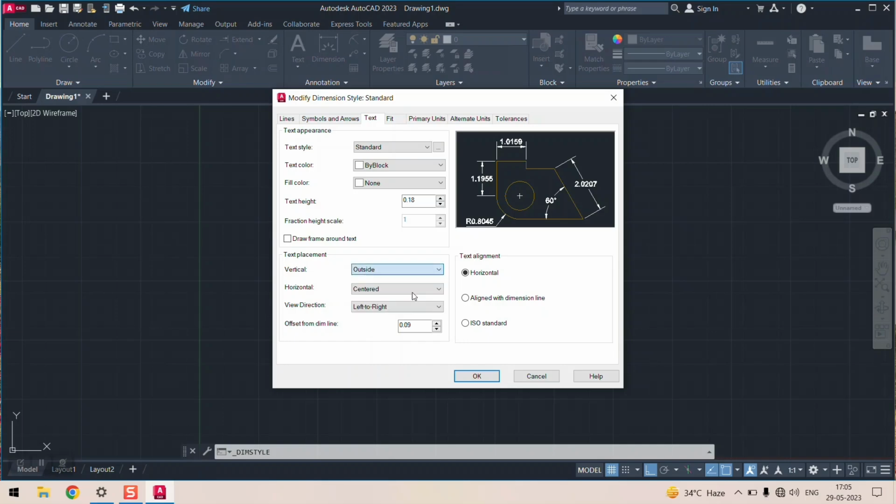So in order to do that, you can bring it completely outside. It will not be inside of your 2D. 2D will be completely, easily visible. Okay. So in order to do that, you can use the outside feature or below. In this particular, below means it will go to the inside of your arrow. Okay. Horizontal means horizontally we are aligning with external lines, or over external lines. So these are the different options which are available with a preview adjacent to your right hand side.